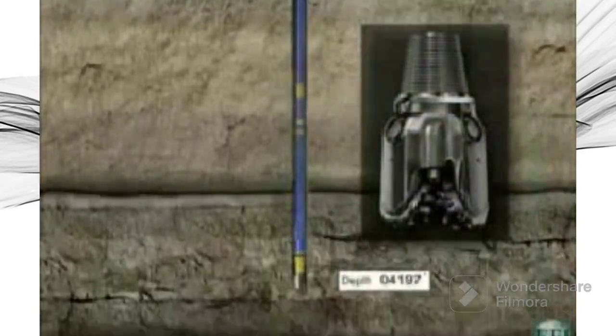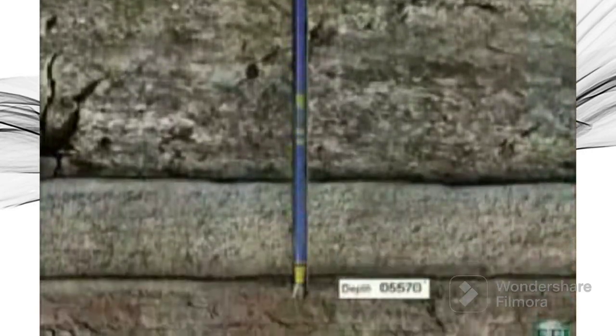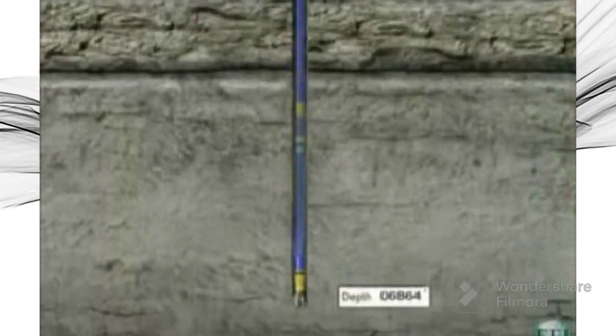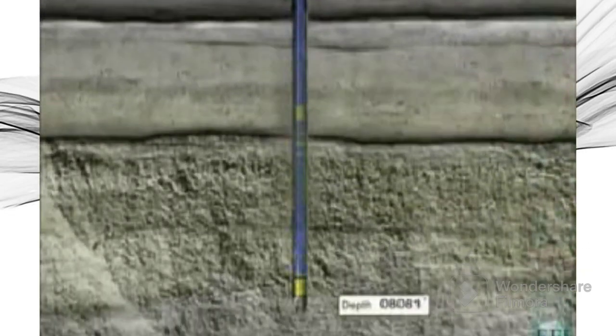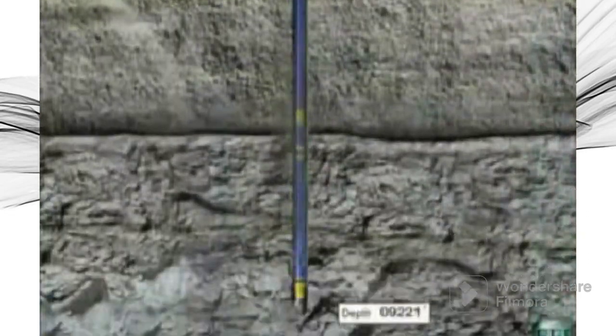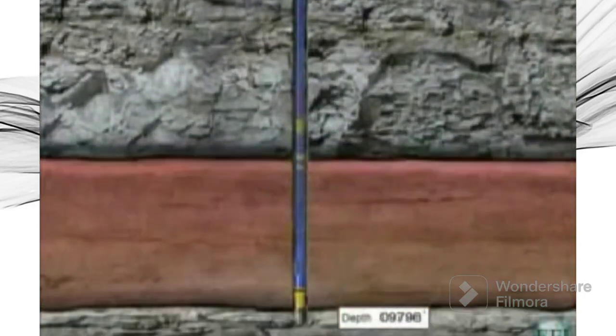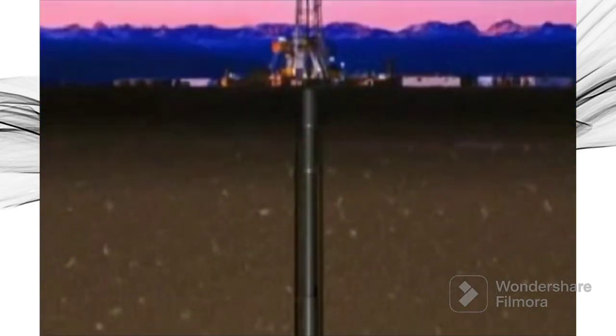The bit is the cutting element used in rotary drilling. As the bit turns, it crushes the rock efficiently and shoots fluids out to carry rock chip cuttings to the surface. New sections of pipe are added to the drill string as the bit drills deeper, until the hole reaches the designated depth. The derrick hand circulates drilling fluid to cool the bit and brings cuttings to the surface for the next operations.